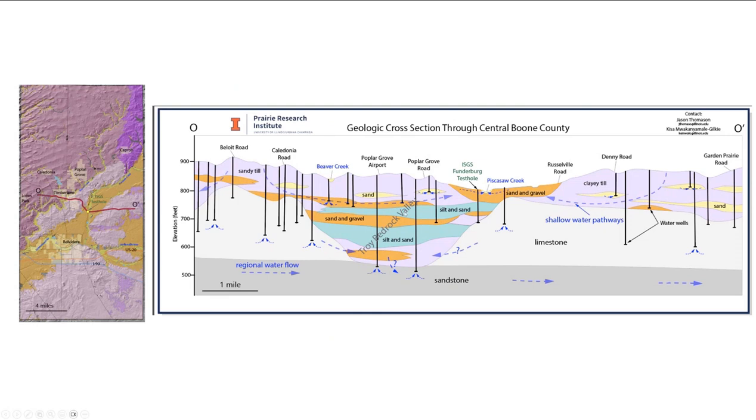So it's not an easy system, for sure. Here's one example where I have an arrow of all these blue arrows are, for example, potential water flow in the groundwater system. One of these is water flow from the limestone into the glacial materials, and it can go vice versa, depending on where water is moving, where the gradients are. Slope of the water table is driving a lot of water flow. Pumping wells are driving a lot of water flow and can change water direction.